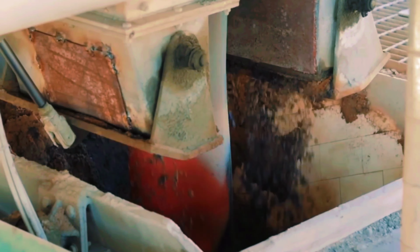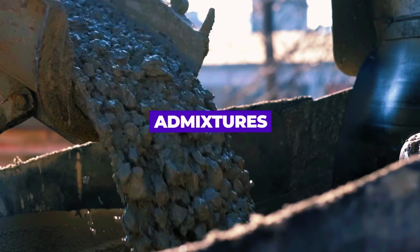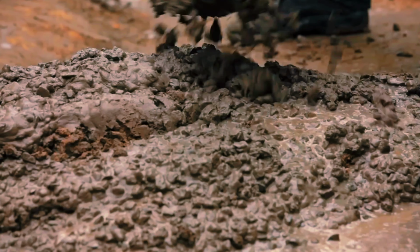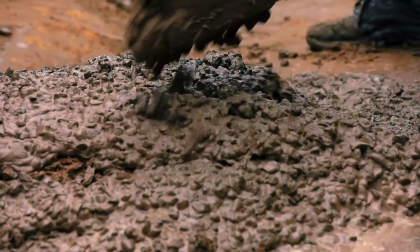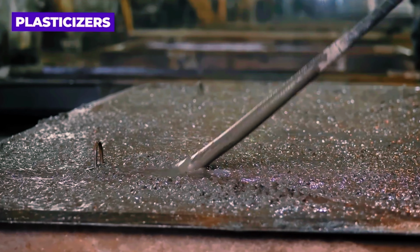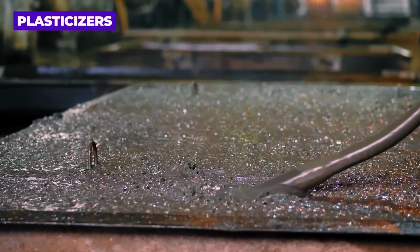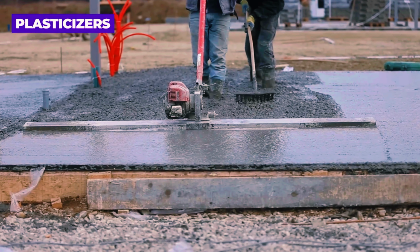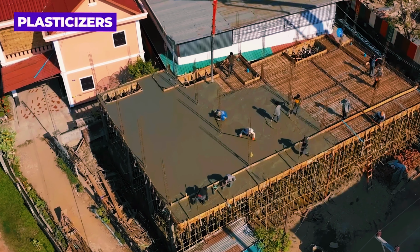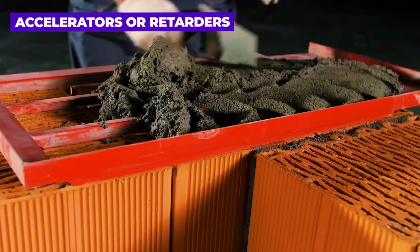Now is a great time to talk about the hidden stars of concrete manufacture, the admixtures. These chemicals offer a range of advantages and may be added to concrete to improve its properties. Plasticizers give the concrete greater workability, which refers to its ability to be easily molded and placed without segregation or excessive bleeding of water, allowing it to reach congested areas.